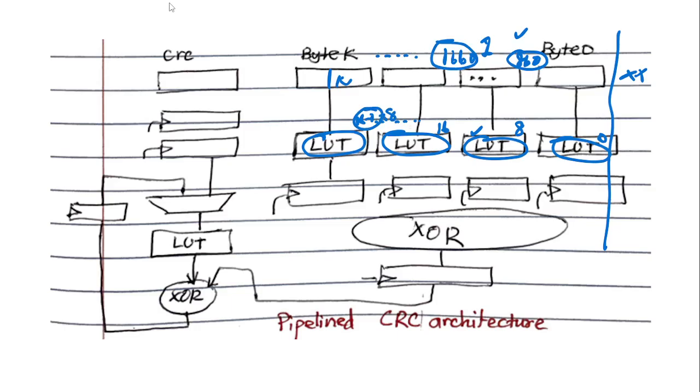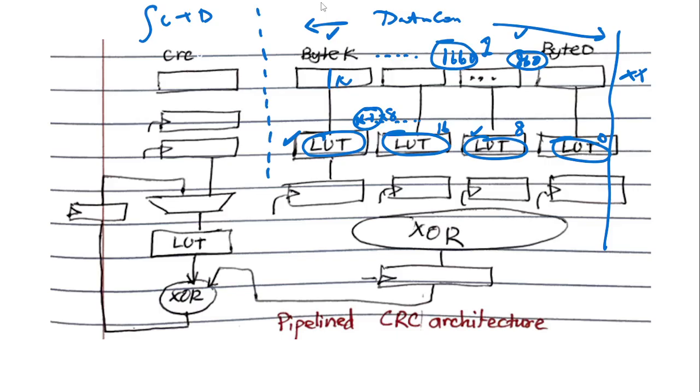We know that. So I think that is the first thing: lookup table design, and we'll look at the code next, so we can see how this code is generated, but it's very similar. For each data component, there are k bytes in the word. This is the data component, right? Just like I said, this is like the Fourier transform. There is a CRC component and there is the data component. The data component is seen as all these data bytes, and on the other side, you have the CRC component, where you have 4 bytes of CRC, the upper byte 3, 2, 1, and 0 for CRC32.